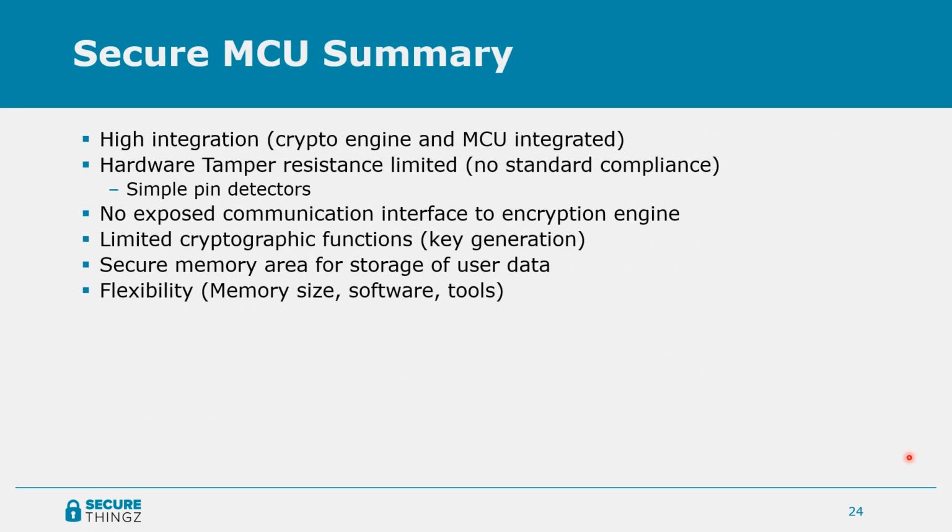As for secure MCUs, they have very high integration. It's one of the key advantages of these devices. So you have crypto engines, crypto enclaves, and the MCU integrated into one device. Oftentimes they do have hardware tamper resistance, but it is somewhat limited, usually to simple pin detectors.